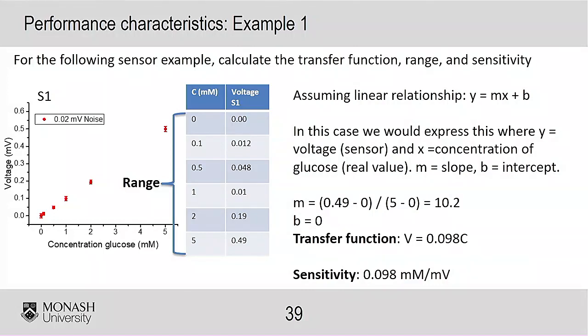But it's also important to note that you could present an inverse transfer function. With our data acquisition systems, if we were to use this sensor, it reads a concentration of glucose and then it gives us a voltage. We then read that voltage into our data acquisition system and we want to display on our monitor what that is. Then we would apply the inverse transfer function to get that data back to an actual glucose value. Okay? But in this case we won't do that, so it's pretty easy.